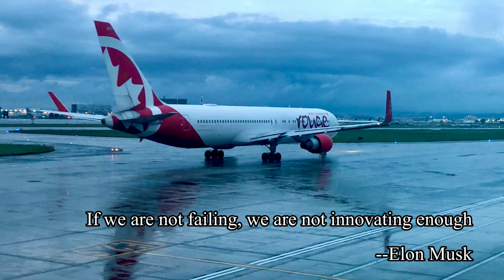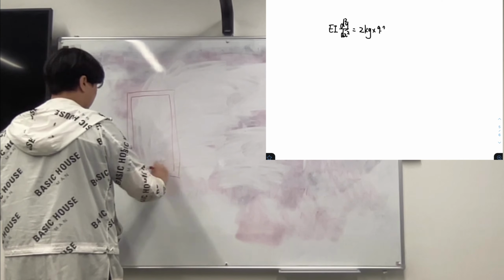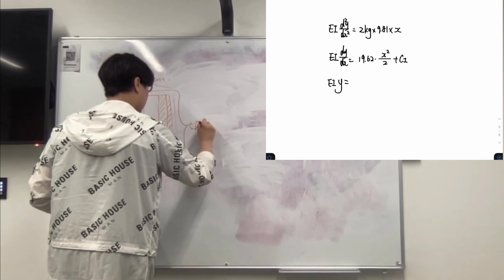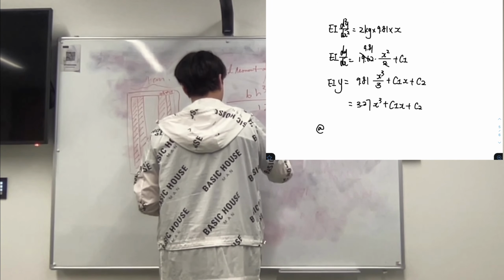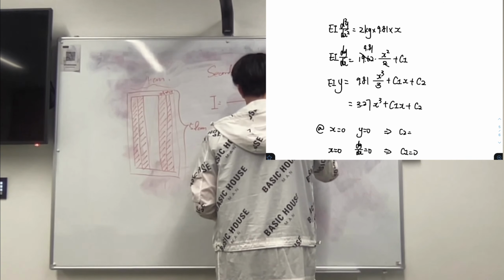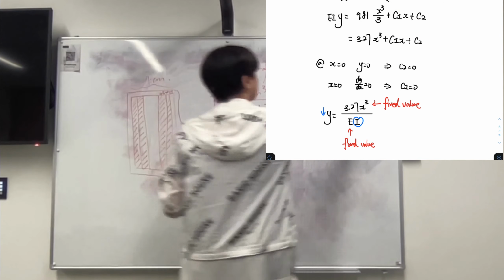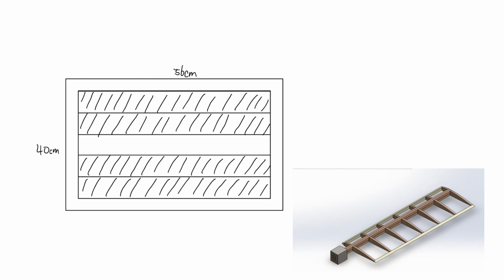And since we're going back to the drawing board to redesign the structure for the next round of testing, starting with calculations again. Since deflection is equal to the second derivative of the tip bending moment over the foam board's Young's modulus, which is a fixed value, times the second moment of area of the cross-section, a decrease in deflection could only be solved with an increase in the second moment of area. With the new design, new hand and computer illustrations are made.